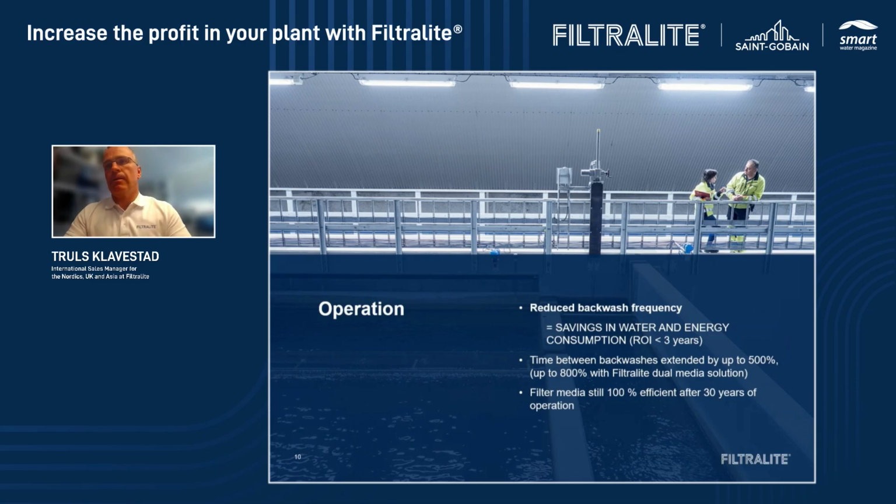Another interesting thing which is important to keep in mind is that because Filtralite is a much lighter material, it's much easier to backwash Filtralite compared to sand. We always recommend in the backwash to use a combination of water and air, because that gives the most efficient backwash.